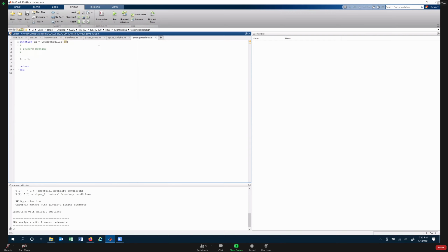So if you look, I have a separate tab here for my Young's modulus. E of x is equal to 1. We know now, because we took this class, this E of x could very well be C, right? It's our C matrix, and how many elements could it have if we're talking about a fully anisotropic material? 81. Yeah, it can be a 9 by 9. So what type of material am I assuming by just having a scalar here? Linear isotropic. Exactly. So I've got my linear isotropic material property here. This could be set up as a matrix if we wanted to.